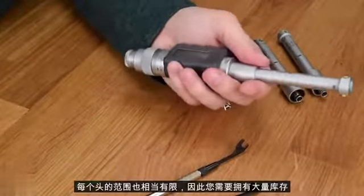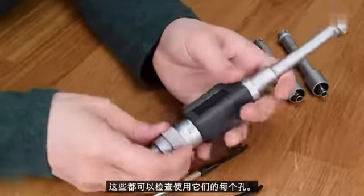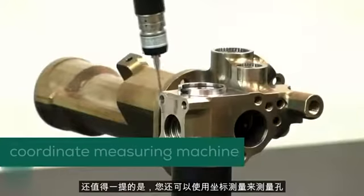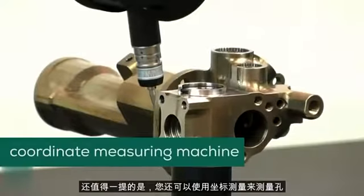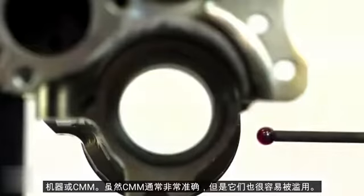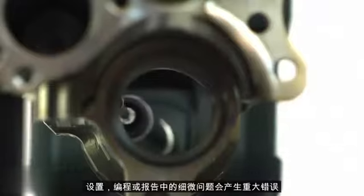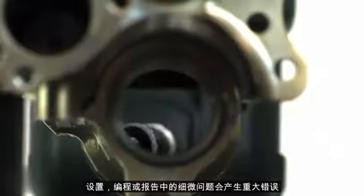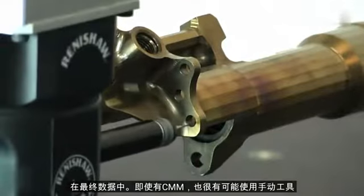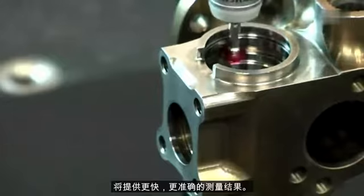The measurement range of each head is also fairly limited, so you need to have a pretty large inventory of these on hand to be able to inspect every bore using them. It's also worth mentioning that you can measure bores using a coordinate measuring machine, or CMM. While CMMs are usually very accurate, they can also be easily misused. Very minor issues with setup, programming, or reporting can generate significant errors in the final data. Even when a CMM is available, there is a good chance that a manual tool will provide a more accurate measurement more quickly.